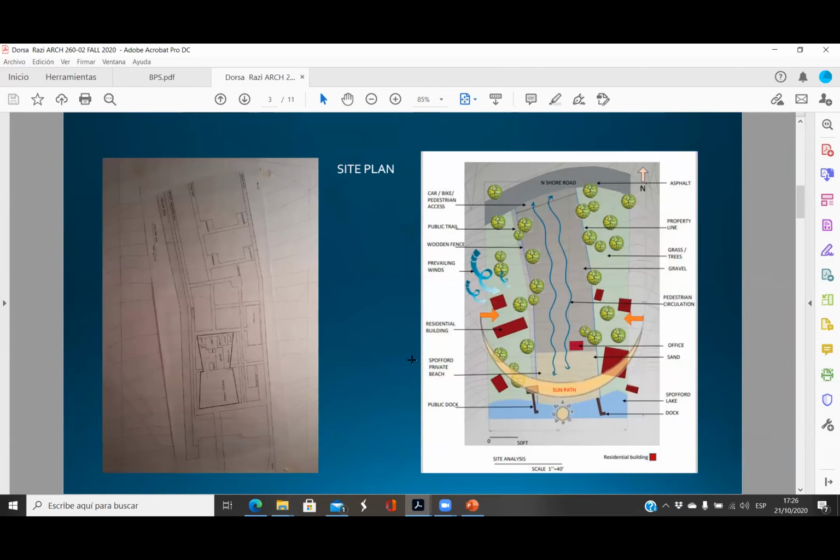Well, at the end you should add, because we have the site plan here, and I think this is nice. And if you add here at least the shape of your building, I think it will help understand what you have done. But I like this site analysis. We have the north sign. Usually when we are looking at the site plan, we have the roof plan of the building, because here you have a lot of walls and we can't tell what this is. Okay, so for site plan, use the roof plan of your building.